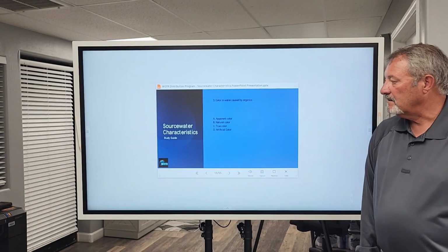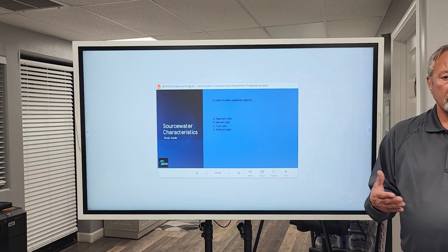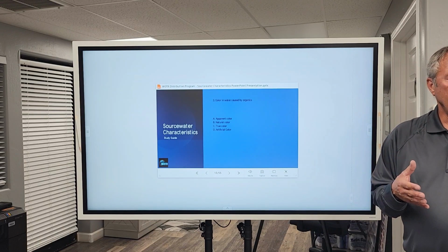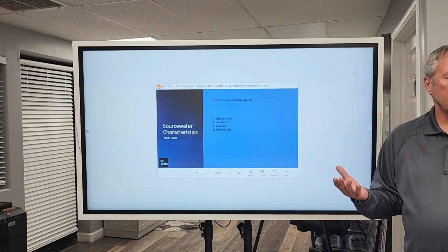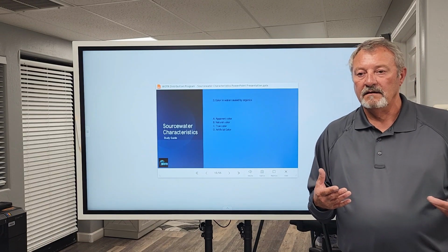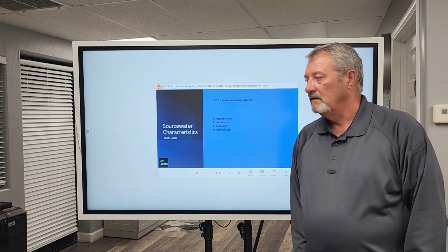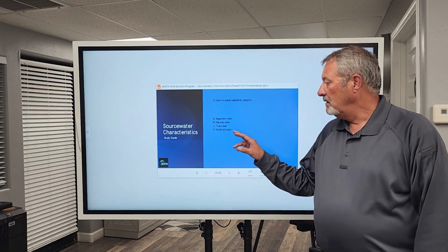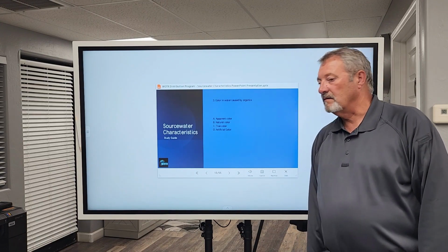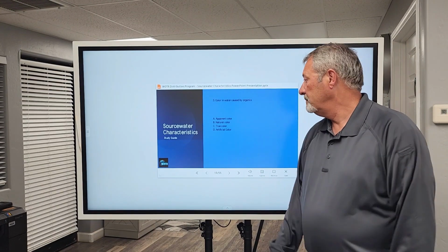When it's caused by organics, that means this is surface water. Surface water, when it's sitting on the ground, in lakes and rivers and streams, has dead, decaying vegetation. So tannic acid from leaves that are decaying can leach into the water and cause color, brown or green colors. We call this true color. True color, C, is the correct answer. It comes from organics that are in the water.